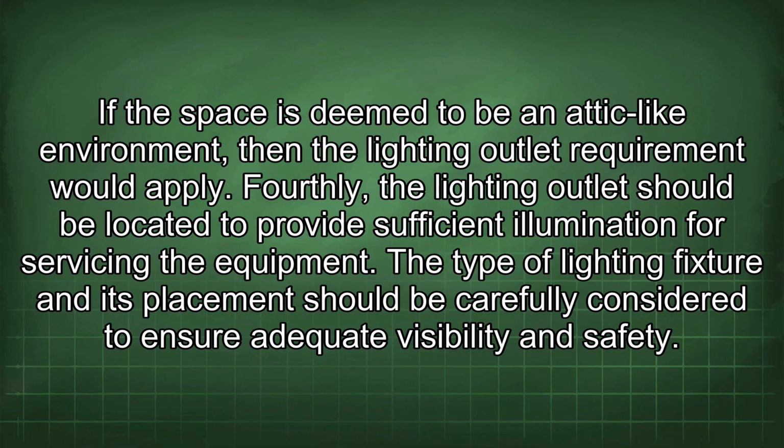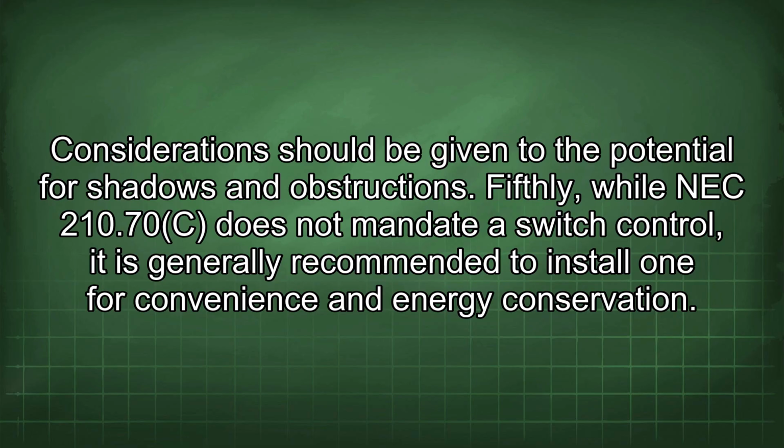Fourthly, the lighting outlet should be located to provide sufficient illumination for servicing the equipment. The type of lighting fixture and its placement should be carefully considered to ensure adequate visibility and safety. Consideration should be given to the potential for shadows and obstructions.